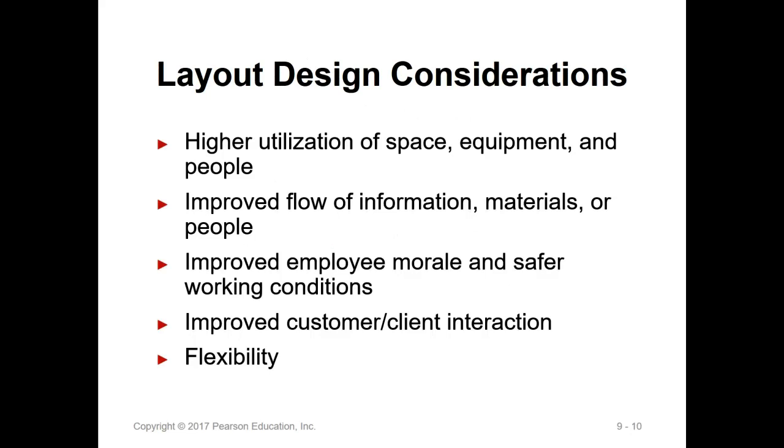And layout design considerations include, of course, trying to make high utilization of the space, whether the space, the equipment, or people. You don't want to idle the equipment, because even when idling the equipment, you still have to consider the depreciation, because you paid for this equipment in the beginning with a chunk of money.